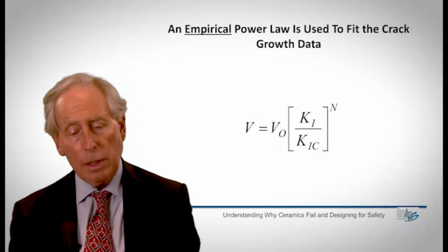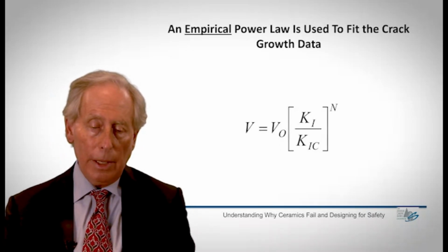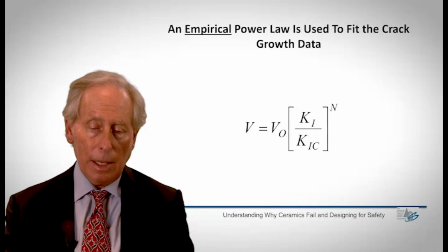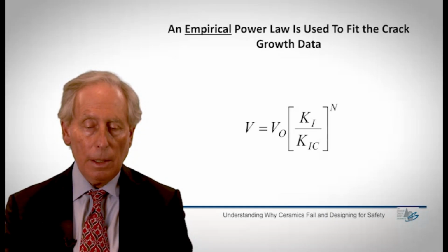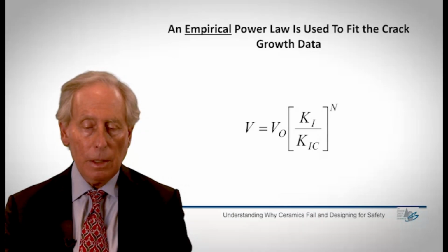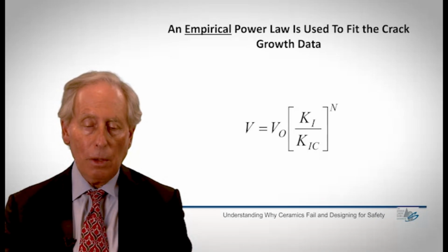So instead of that logarithmic function, we chose to use a power law. The critical stress intensity factor here is really just a number used to avoid dimensions in the equation. So this is an expression of crack velocity as a function of stress intensity factor with an exponent n.